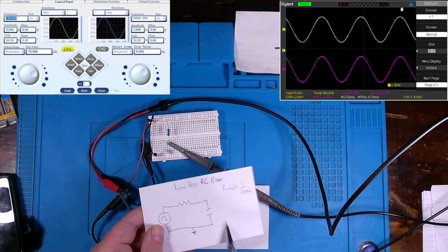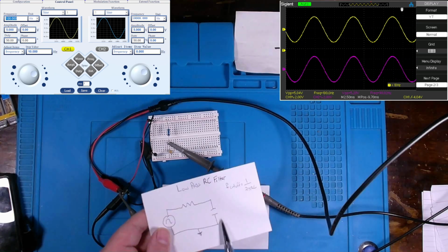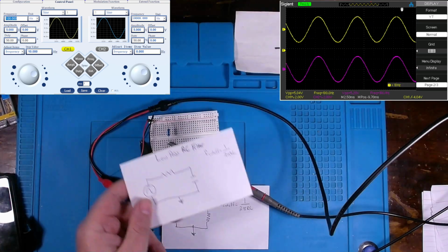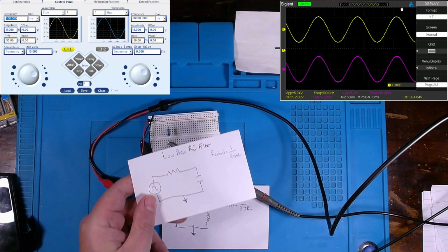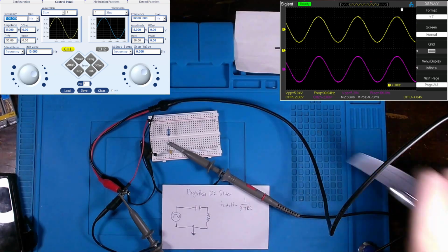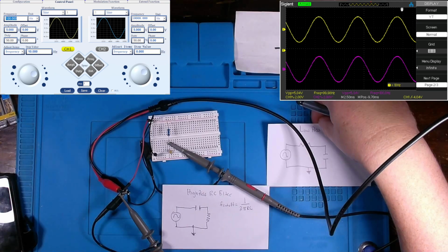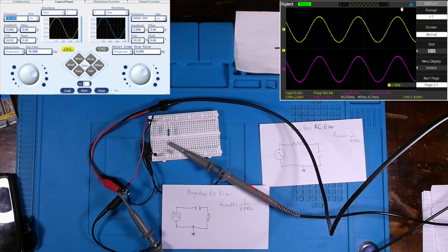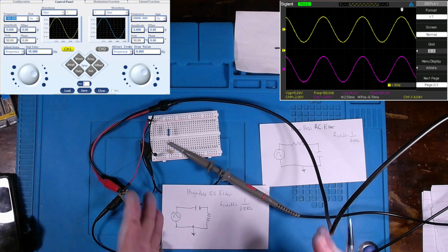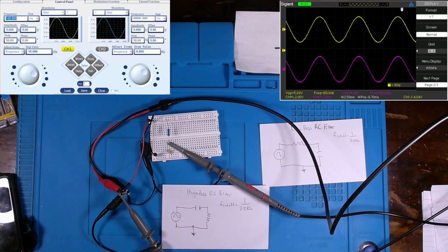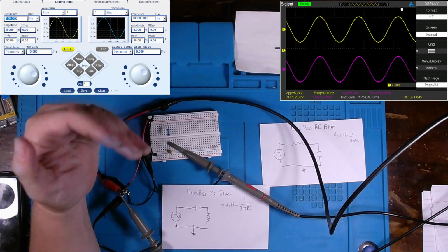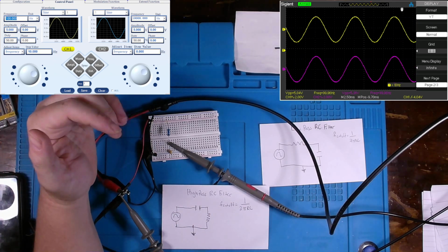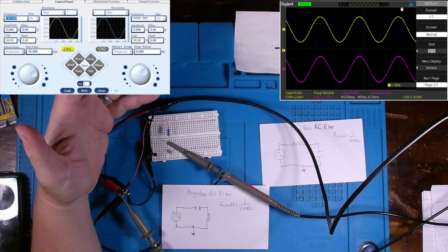You swap the capacitor and the resistor in the circuit, which comes first. Okay, that's how you create a high pass RC filter. All right. And so let's say I wanted to get rid of the bassy tones out of whatever I'm producing now. Actually, in fact, I was considering doing this for my radio restorations.